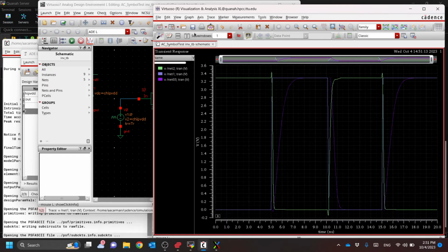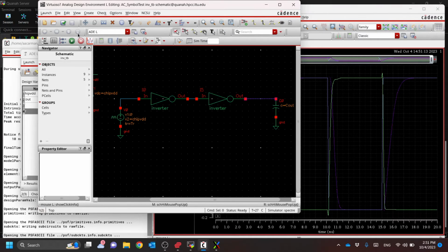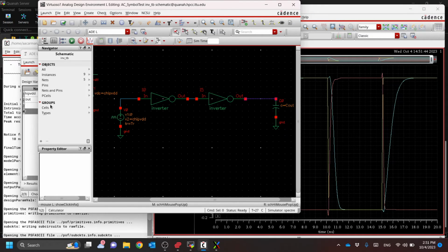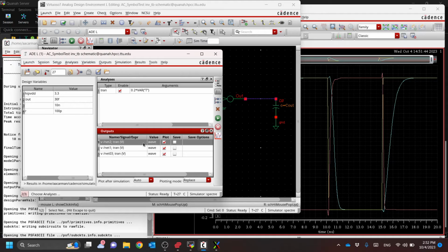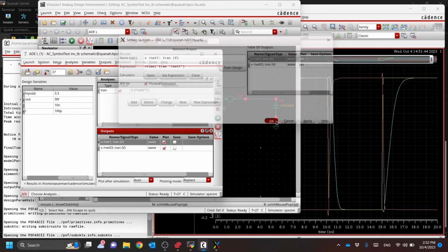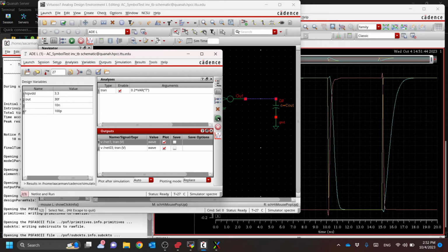See that it's dashed this time, but if we rerun it, maybe it'll change. Okay, so now you can see maybe if we get rid of this, let's see. Our net 1 is our input, net 2 seems to be the first output, net 3 is the second output. So let's go ahead and go back to this guy and let's just get rid of net 2. Maybe we don't care as much. We can right click it. We can just delete. Okay, now it's gone. Hopefully if we resimulate, we'll be back to it.